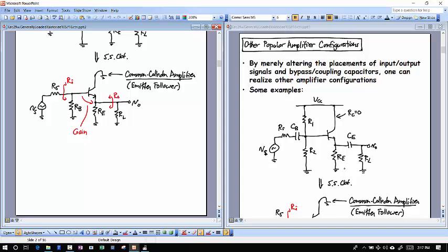So in this case, if I took CE, so CE is just the capacitor that's attached to the emitter. I'll always call that CE. The E means emitter there. And so if I took that CE down in parallel with RE, then the small signal circuit would ground the emitter. And that's what we've been doing.